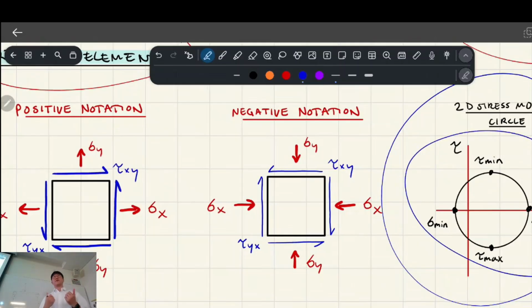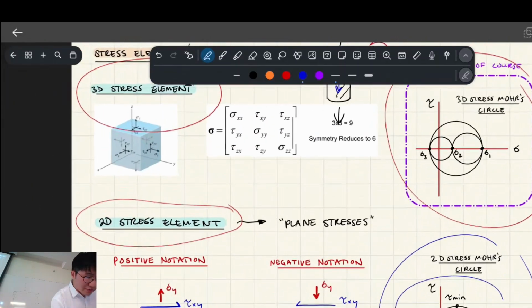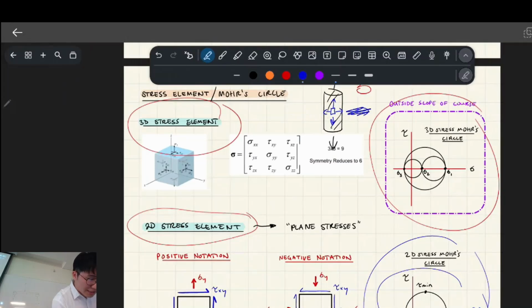The other thing is you can have a positive or a negative axial stress. So we just take one direction as positive. For the example of something being pulled in tension, like this tension rod, we'll say the tension direction is positive. So if it's experiencing 100 MPa of stress in tension, it'll be positive 100.